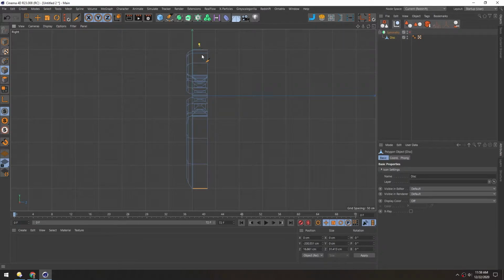And now I'll just single click here, hold shift, single click again. And if you want, you should be able to drag this around to make the cut wherever you want it. And holding shift will snap it. So if I want to move it back a little bit, I can scoot this. It looks like that committed it, so I'll just undo that and just do it again. And that looks good. I'll hit escape to commit that.